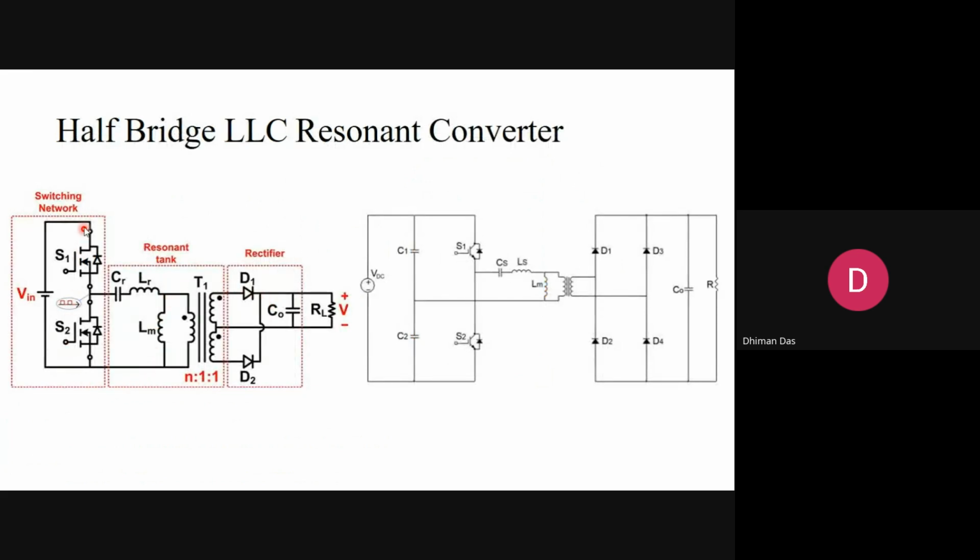Similarly, the primary side can be replaced with a half bridge cell, but when you replace that, your voltage will no longer be a plus-minus swing. It is a plus and zero swing. So your gain will be directly half of the previous one, half of the full bridge. But now in this case, your current is pulsating in nature.